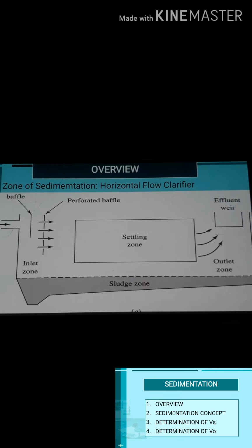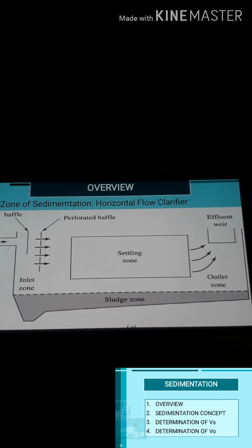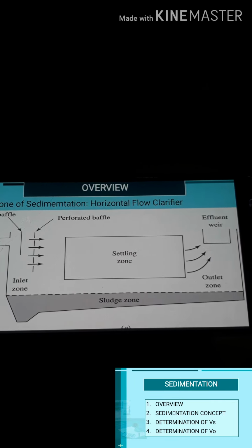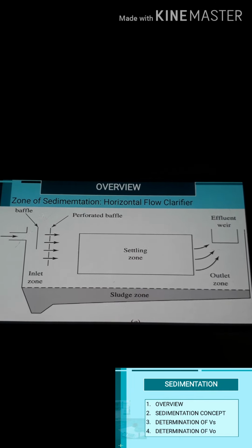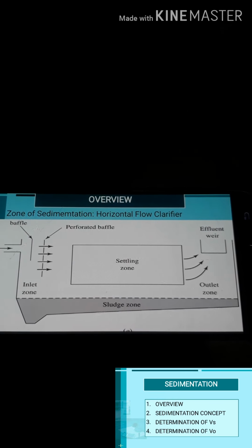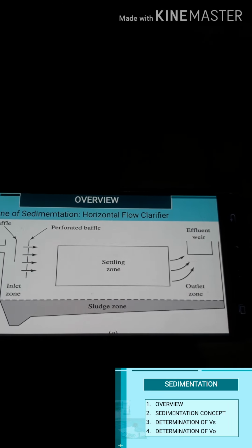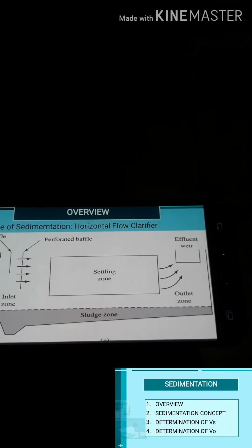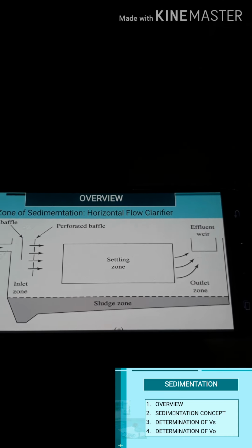With an improper design, the inlet velocities may never subside to the settling zone design velocity. Typical design numbers are usually conservative enough that an inlet zone length does not have to be added to the length calculated for the settling zone. In an accurate design, the inlet and the settling zone are each designed separately and their lengths are added together.